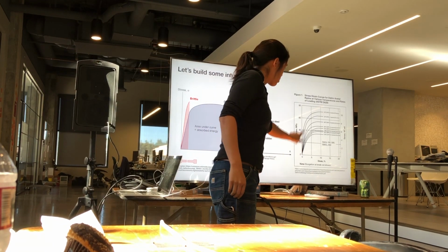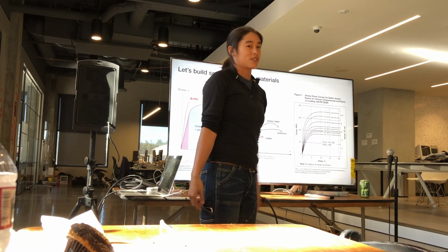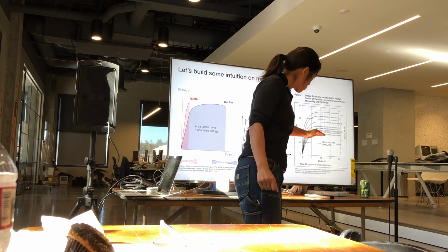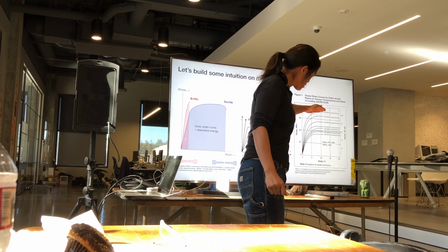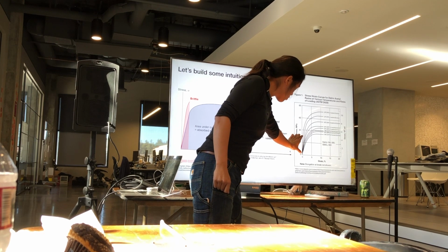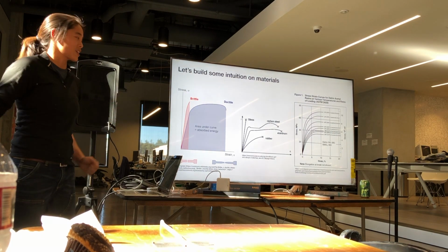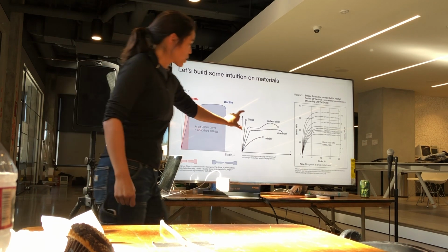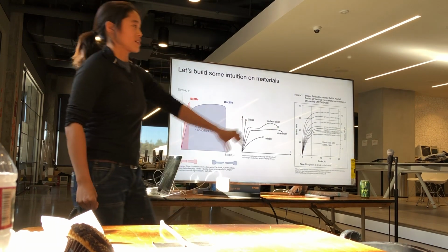These are some curves here of a material called Delrin, which is what all the kits are made of today, and a lot of the demos are made of as well. This is as it varies through temperature, from 23 degrees Celsius all the way to 100 degrees Celsius. And what you can see here is that the linear region that we have to work with, the elastic region that we're so interested in, is, to begin with, quite small even at room temperature, and increasingly smaller for plastic when it warms up.